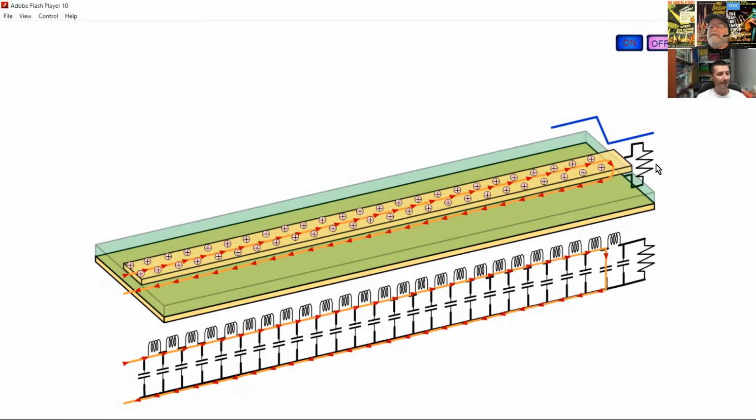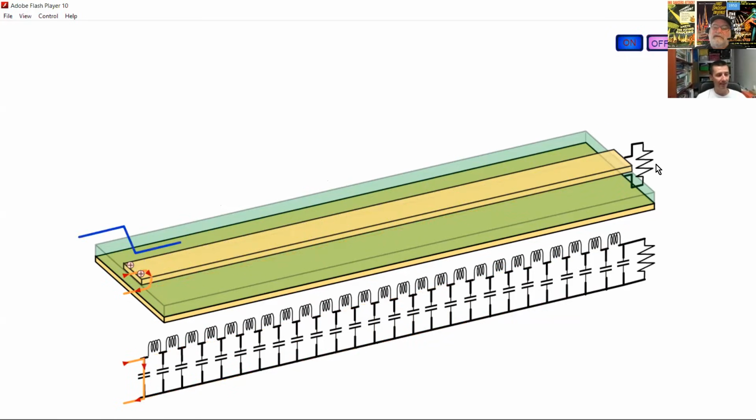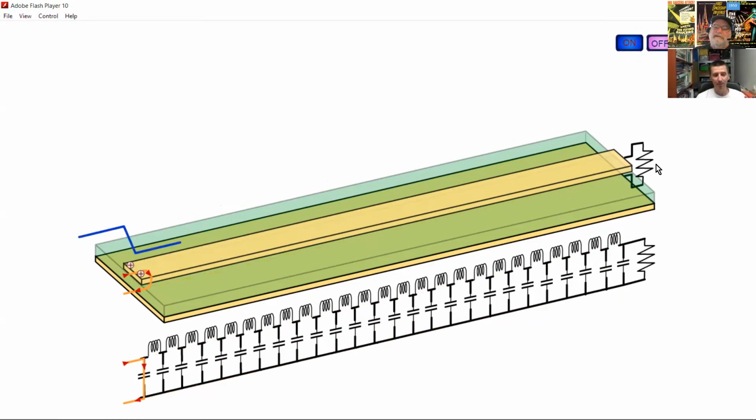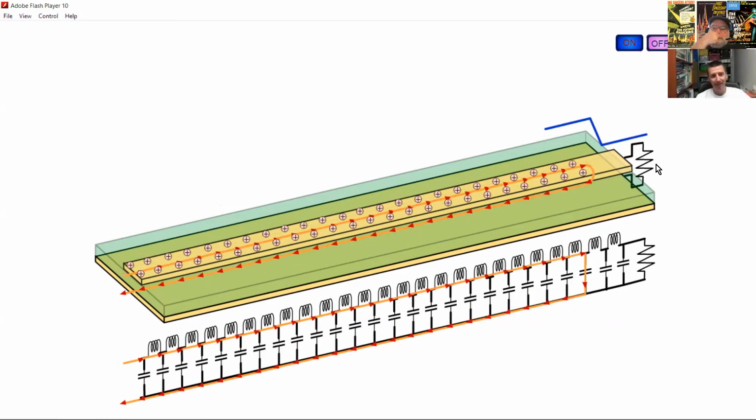And then, I like the picture down there because you can very nicely see that basically, because there is the edge, there are higher frequencies, and for higher frequencies, the capacitor will basically be a short circuit. So that's where you get these short circuits going down. That could also be one of the explanations, or am I wrong?